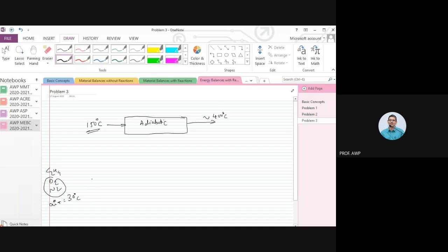All right, jokes apart. So these are going to be available at 30 degrees centigrade. That means if I want the reactor to be supplied at 150 degrees centigrade, I need to heat it up, right? I need to have a heater that will heat up the gases, and then these heated up gases will go at 150 degrees centigrade.